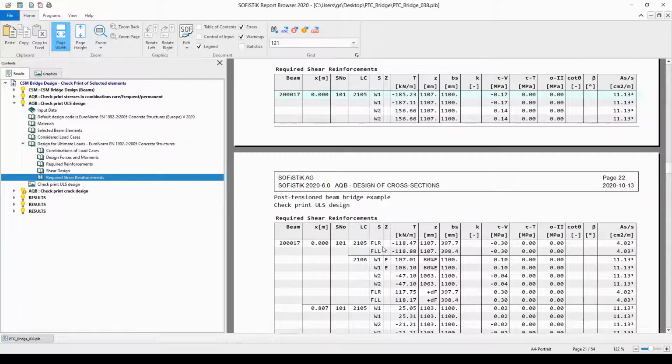Now if we review the remaining two shear cuts within our cross-section, the FLR and the FLL, we can see that they only consist of one part, because the output contains one line per flange cut. This is because we had defined these types of cuts in a different way in the cross-section editor. We instructed the software to create a flange cut and not a web cut, because in this case the calculation of the shear stress is different from the web cut.